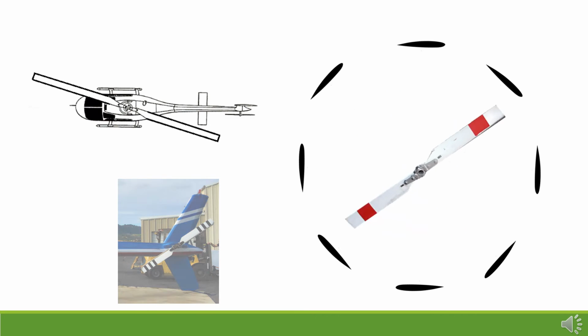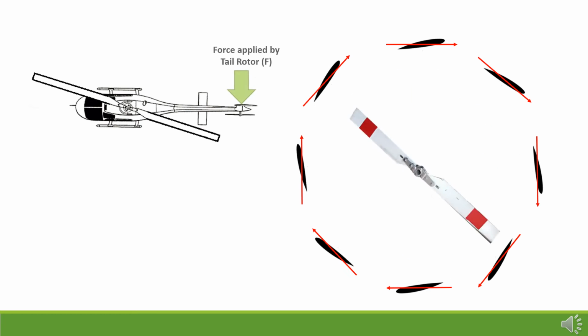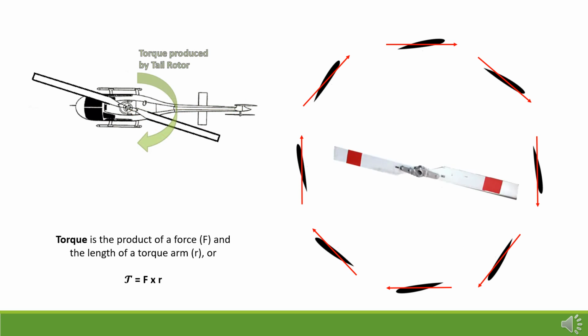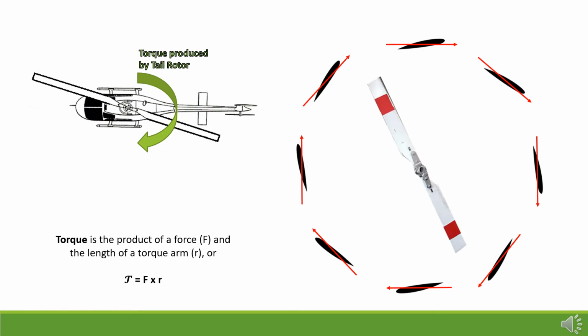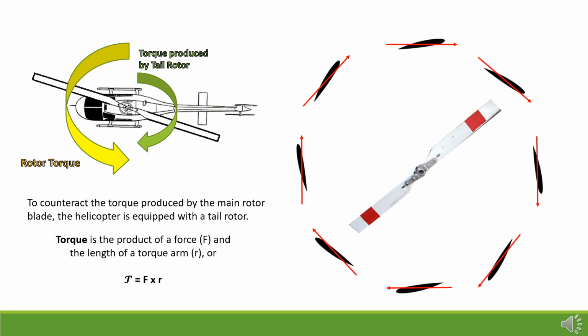The tail rotor is a small propeller mounted so that it rotates vertically or near vertically at the end of the tail of a traditional single rotor helicopter. The tail rotor's position allows it to develop thrust in a horizontal direction. As it is placed at a distance from the center of rotation of the main blades, it produces a torque or rotational motion. One of the functions of the tail rotor is to counter the torque effect created by the main rotor. Tail rotors are simpler than main rotors since they require only collective changes in pitch to vary thrust.